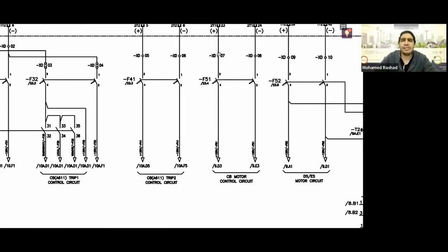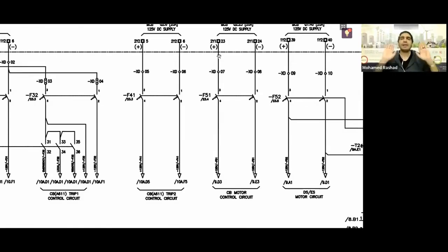Now, I want XD here. As soon as it arrives, you must enter through the terminal block at the beginning to measure from it and then exit to the MCB. Any control circuit like the AC must start with a circuit breaker. The circuit breaker in its schematic diagram must always be labeled in the open position. What should it be? It should be open. All right, great.